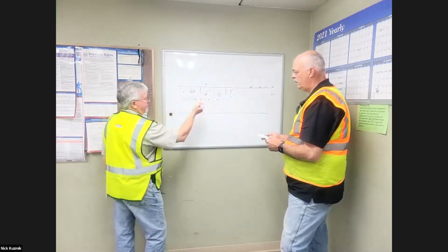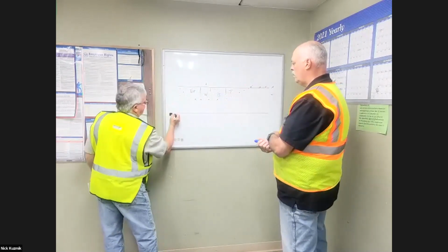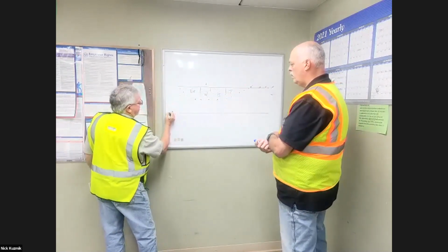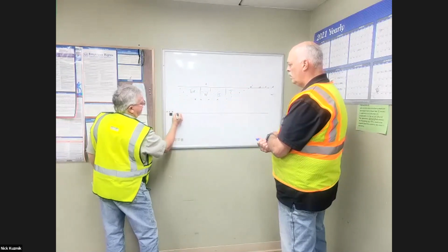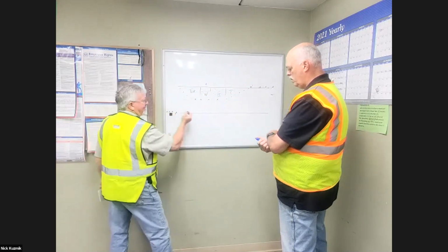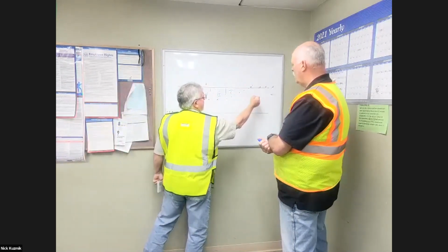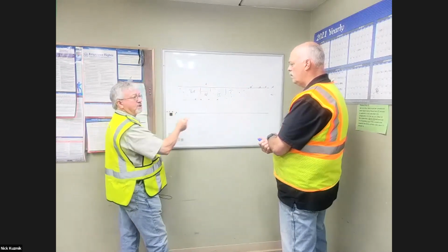And then as you're setting this up, you're also going to have your 3 signs over here, again, set at the same distance. And then you'll have your flagger as well that's going to be pointed here. Your traffic's going to be set up so it can stop and then work its way around through the work zone.